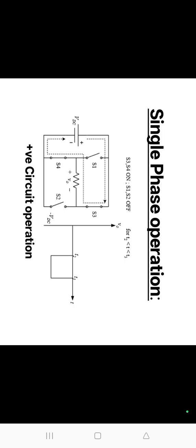During the time of T/2 to T, thyristor T2 conducts. The voltage across the resistive load is minus Vs/2 due to the lower voltage source Vs/2. Thus the load voltage V0 is an alternating voltage waveform of amplitude Vs/2 and frequency 1/T Hz. The output frequency can be changed by changing T.